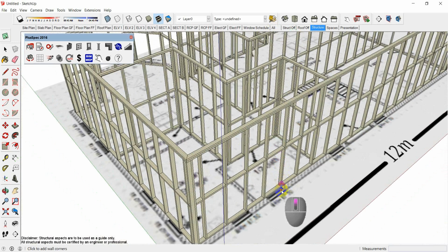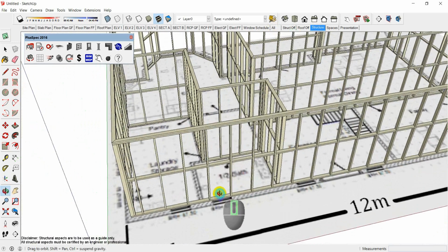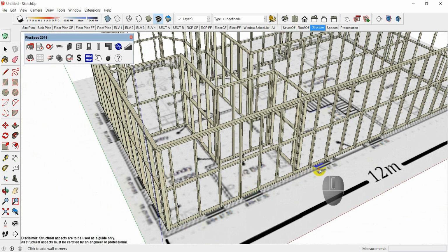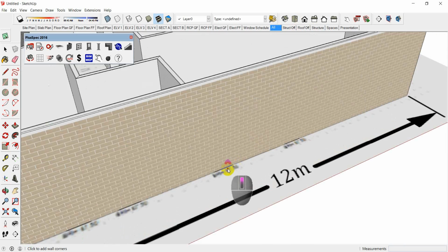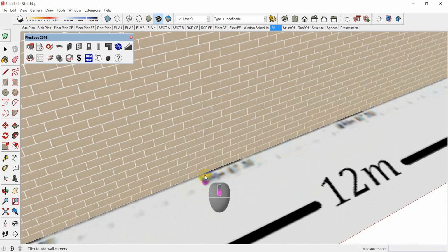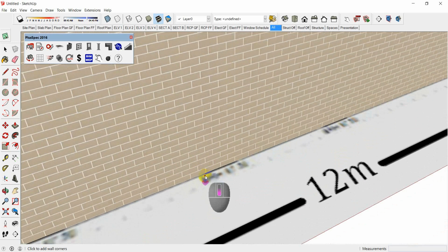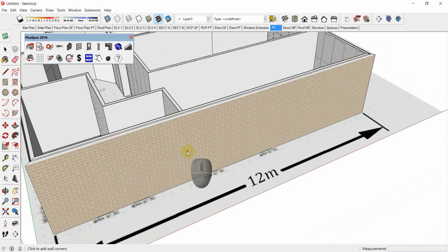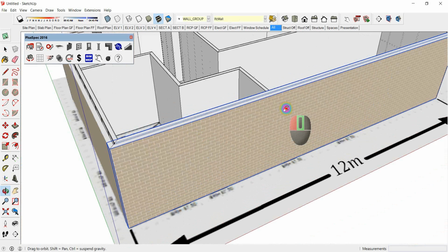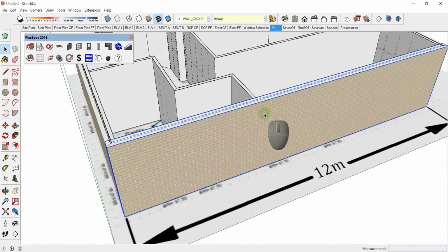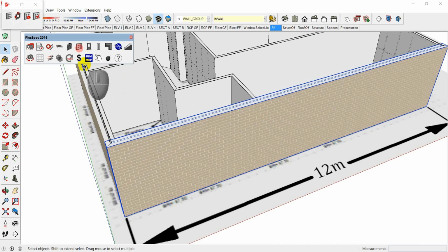Depending on how well the drawing you've got has been done will depend on whether you can see through. So you can actually do windows when you're looking at all, provided you can see where the window is. This particular plan is not too bad, but to make it a bit easier, we made it so that we can see through the plan. So when I click my space bar, it's like a select all. I can now select my wall, and I can go in and put windows in.